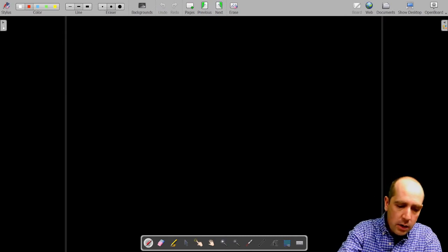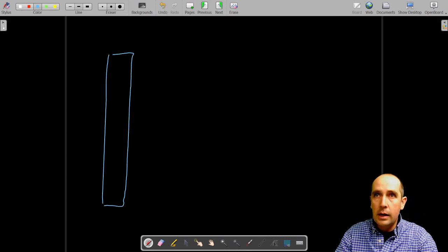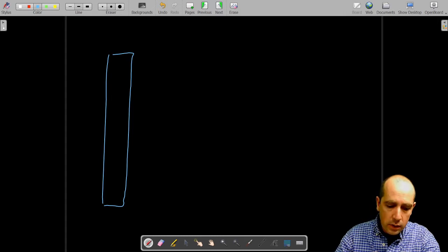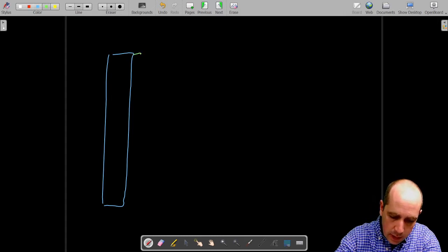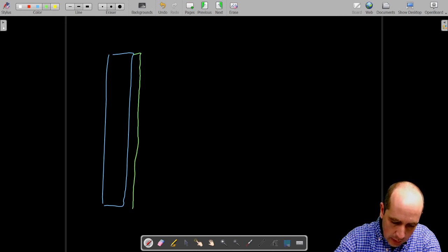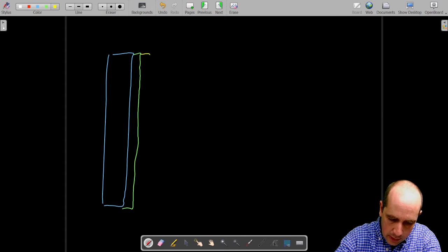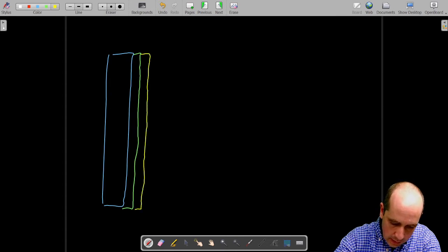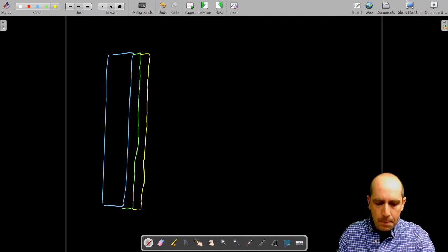If you think of your wafer, I will put here a cross section of the wafer. So this is the initial bulk grown wafer. We could grow, for example, N or P doped layers, and alternate between P and N, and there I will produce, for example, a diode.